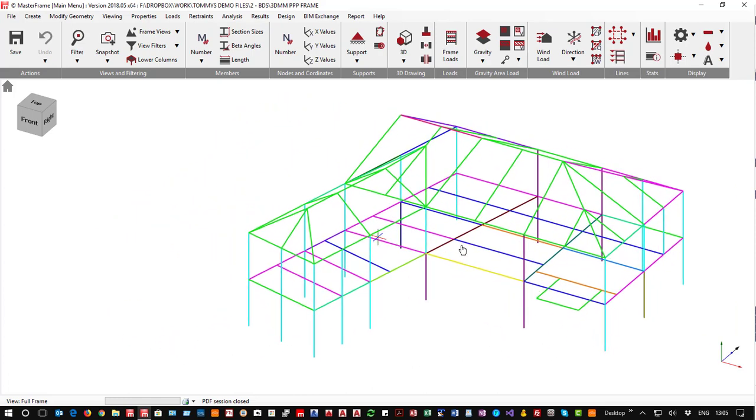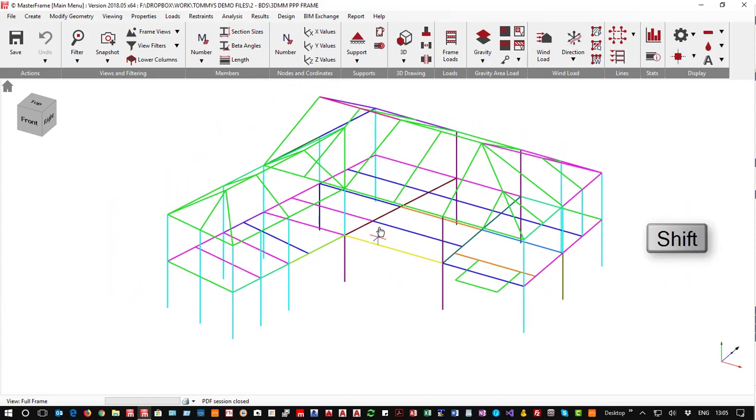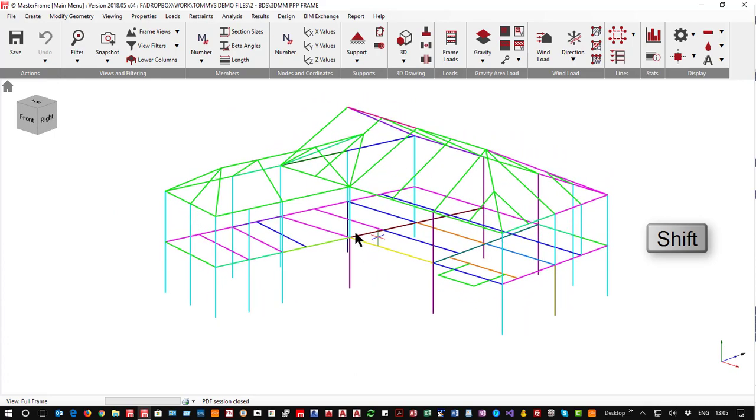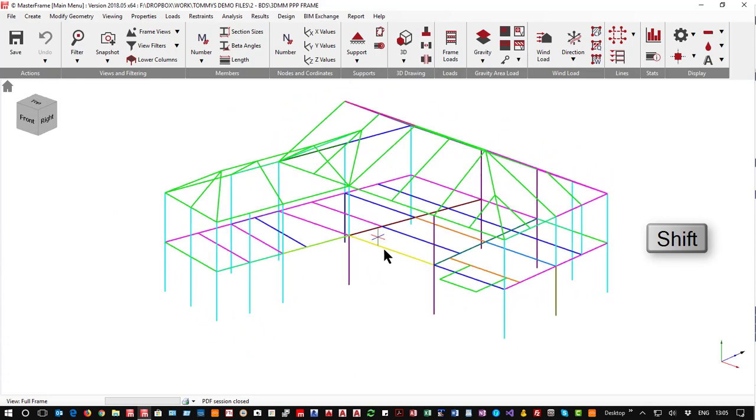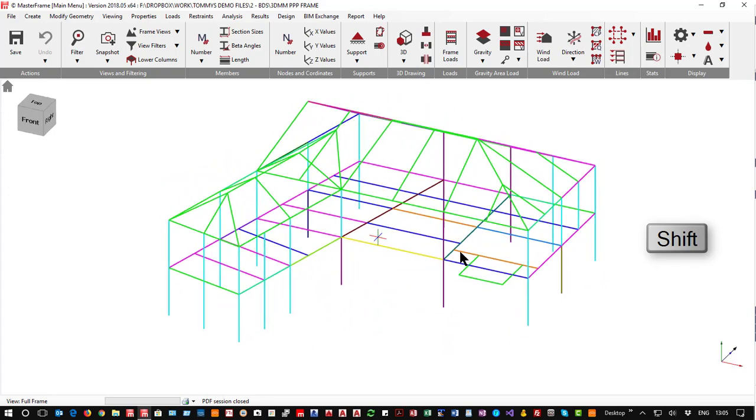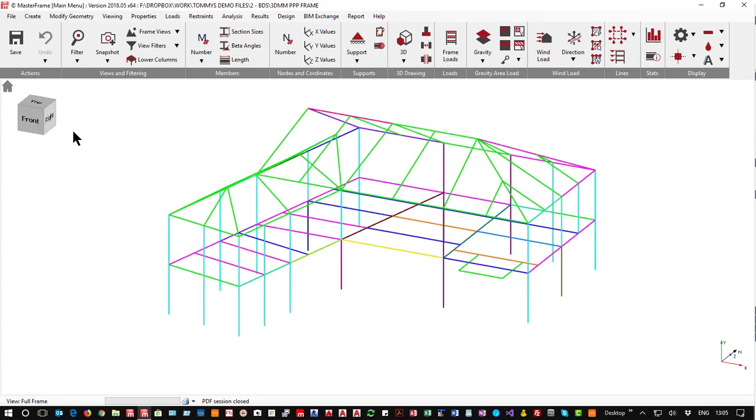Clicking with the middle mouse allows you to pan as well. Rotation is with the shift held down, and you just then rotate up and down. Naturally, you've got these tools as well. So that's the easy bit. We've done away with one or two features from the toolbar, and we've made others more prevalent. We've reorganized into different groups. So I'm going to skip past this area first, because it comes into really the second part of our presentation.